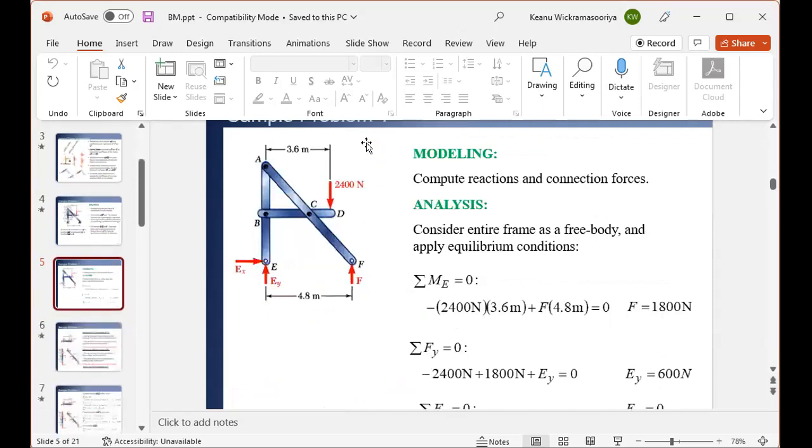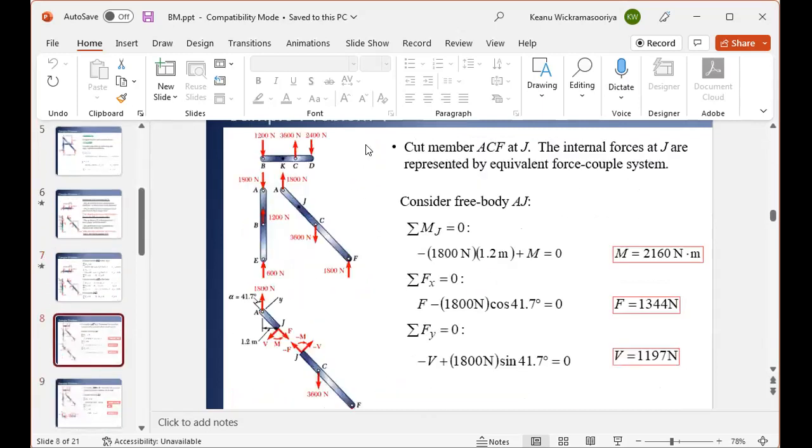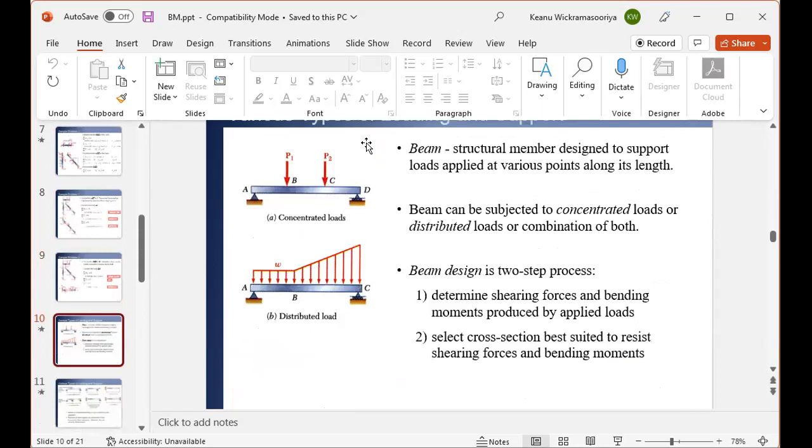But when you have a load like this, with two loads on a simply supported beam, you will see that when you make a cut at an arbitrary place, you need not only a force for the equilibrium of that particular part, you also need a moment.